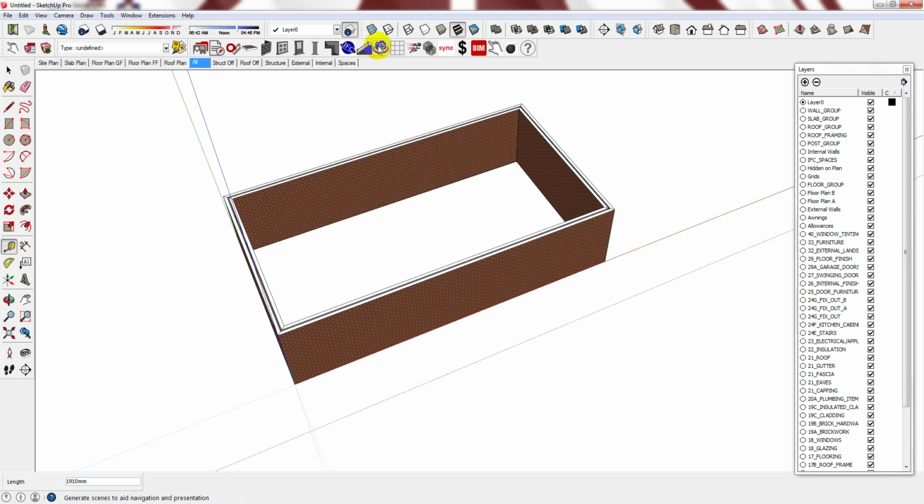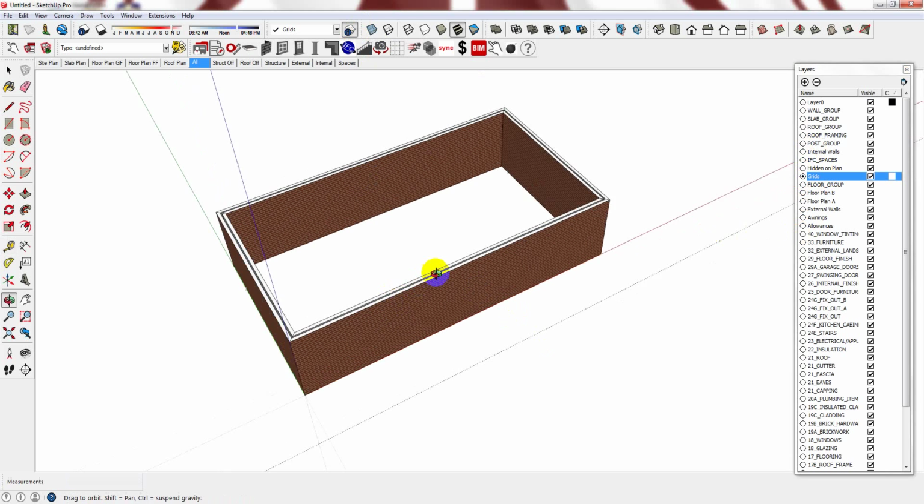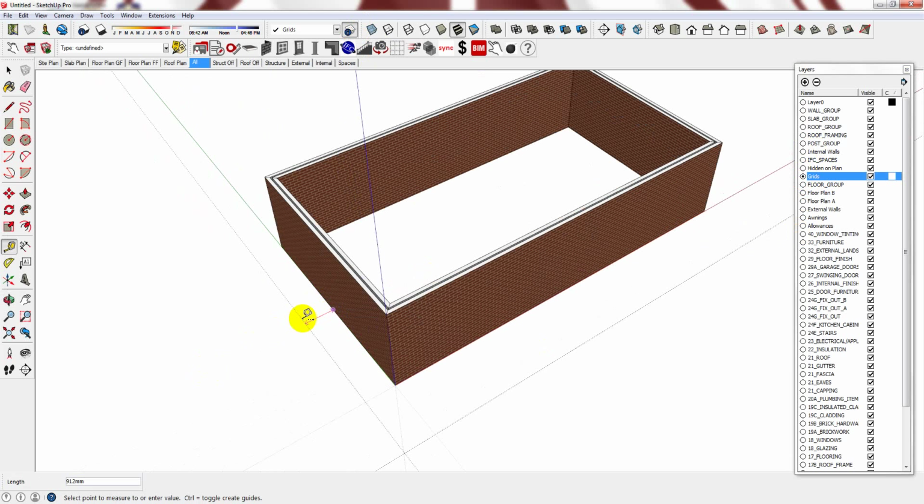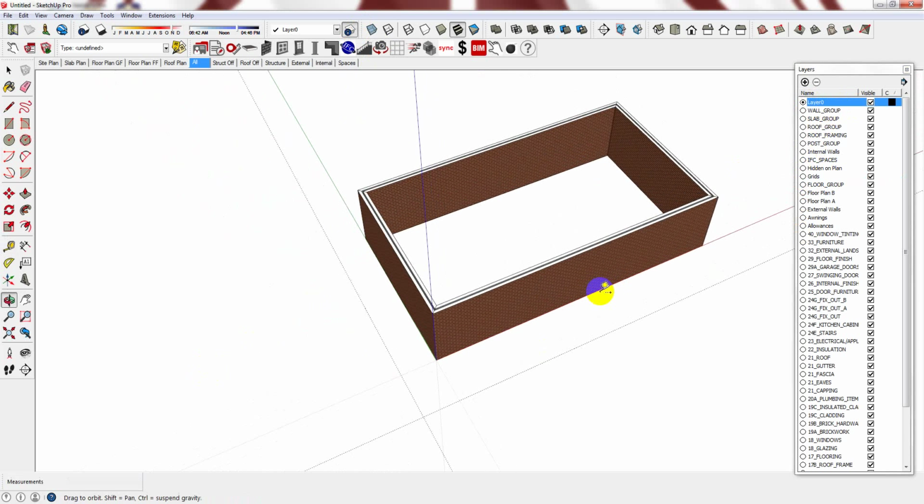As soon as you have created a scene using the Generate Scenes tool in Plusspec, the grid layer will automatically be created. So all you need to do is activate it, and every time now that you draw a grid or a line, it will be associated to that layer. Just make sure you go back to layer 0, as it's best to keep that as the default.